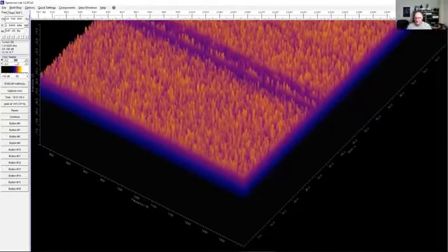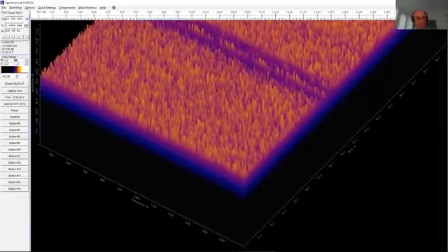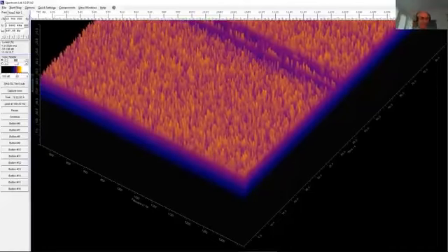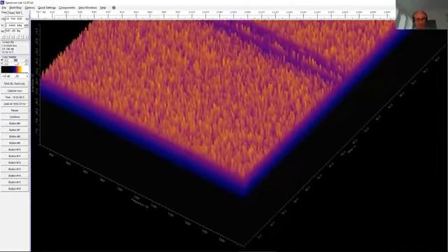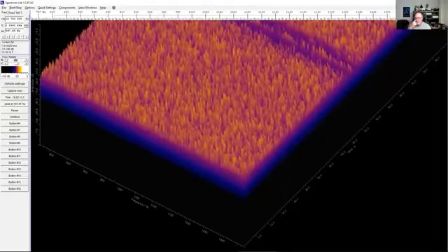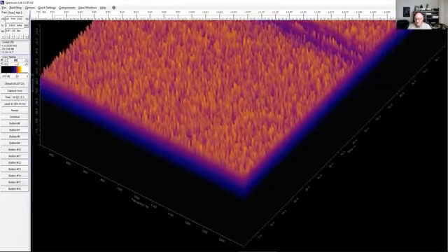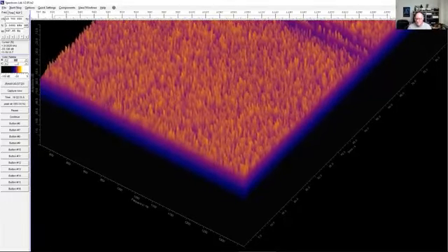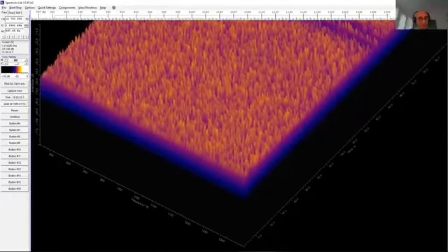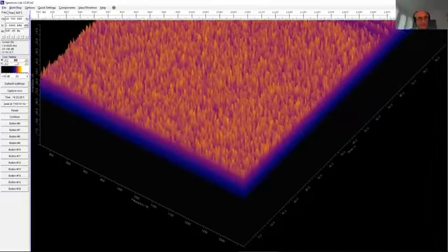Yeah, absolutely fine. But the other thing I've learned is that the dongle that I'm using, I have to make sure that I put an extension to keep the dongle away from my laptop. Yes. Because it actually does make a difference. That's right. So this is one of the reasons I've got the Fun Cube, because the Fun Cube rejects interference. The RF stages have got a bit more protection in it. It's taken me quite some time to discover that, by the way.